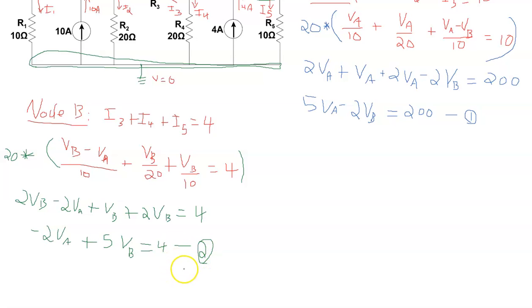And so now, a substitution example here, because there's only 2 equations and 2 unknowns, is relatively easy. You notice that with mesh analysis up there, you would have had 5 mesh equations. The voltage drops across the current sources would have had to be found, and simplifying the circuit before you start would have been necessary because of too many equations, right? And so here again, because there's only two equations, your substitution solution is a lot easier, of course. So that's one of the benefits sometimes of nodal analysis.